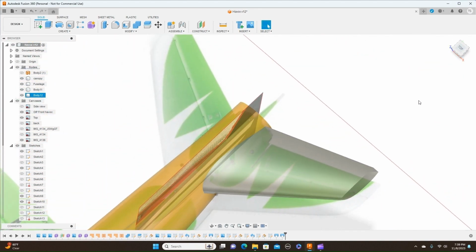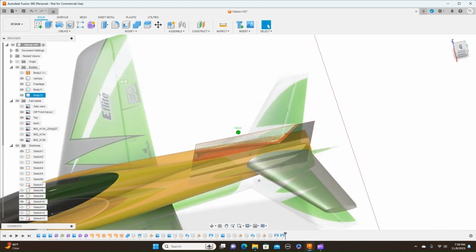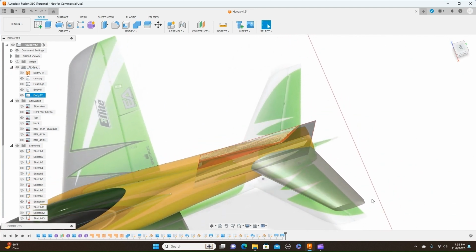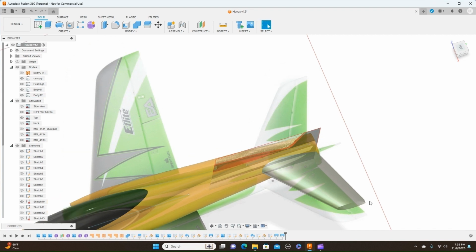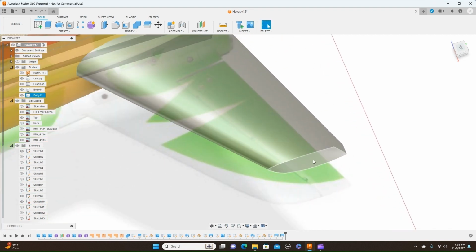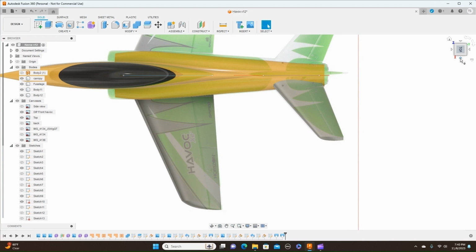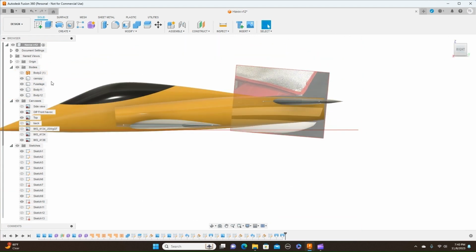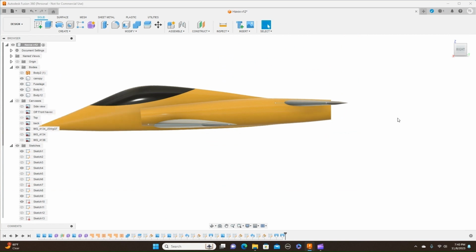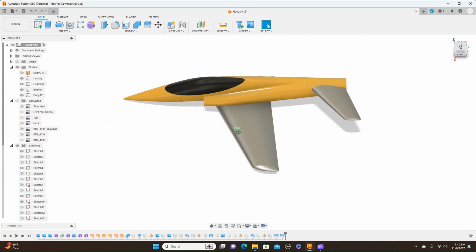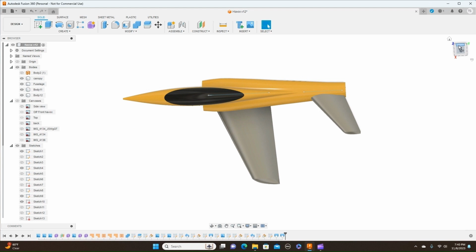Now what I've noticed with Fusion, sometimes doing these tips this way, you can have some problems, and you may have to adjust your geometry on this to be able to loft this. So I had to adjust just a little bit, but it still looks all right though. So now we've got that. So I cut the canvases off. That's what we have.